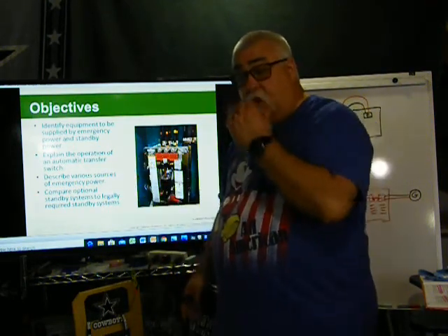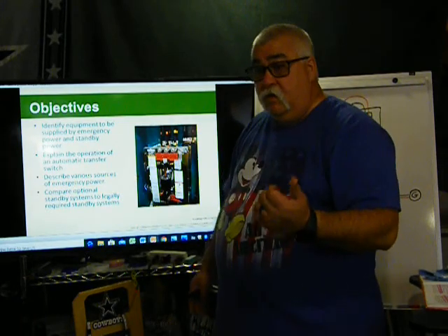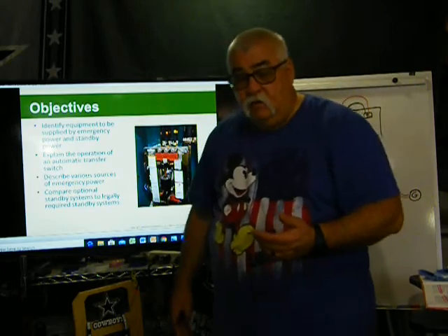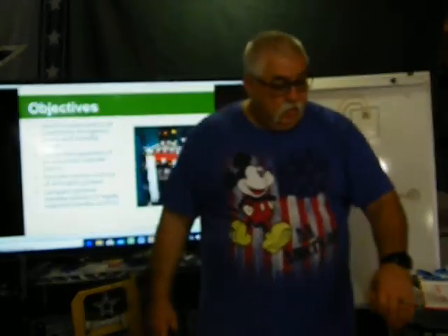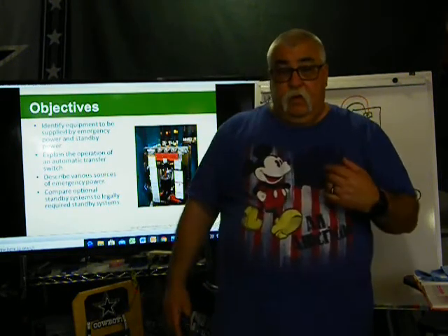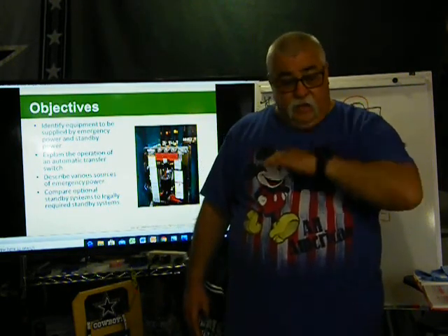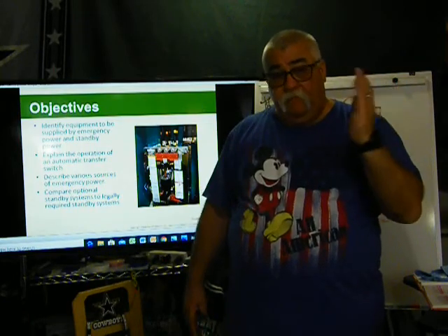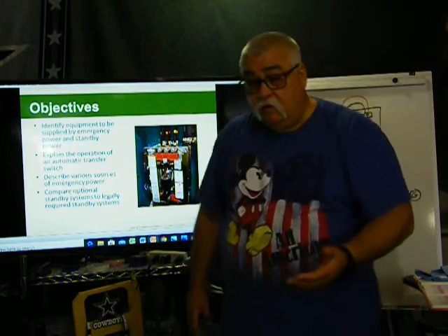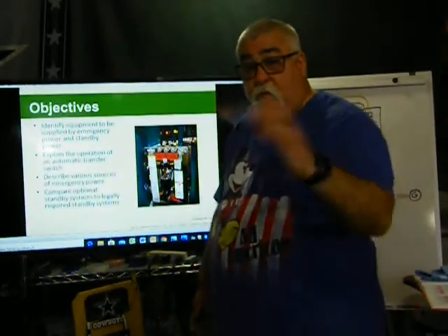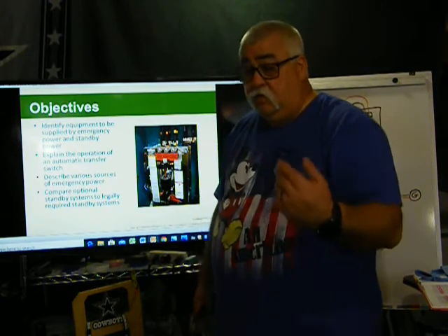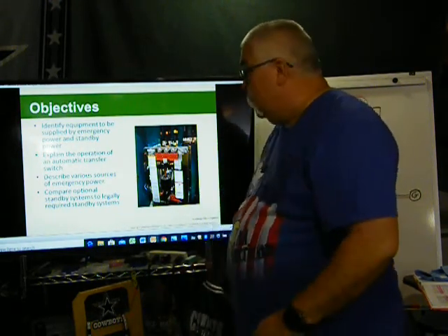We would always have to let everybody know a week ahead of time, and then let them know 24 hours before we did the test. Why? So you can turn the computers off. If someone is working on something and gets up and walks away from the computer, that quick off and on from normal power to emergency power can cause any information in the computer to be lost. So we did it as a precaution so people can turn things off. If things were sensitive to power going out, we told them ahead of time. It's all part of the test.